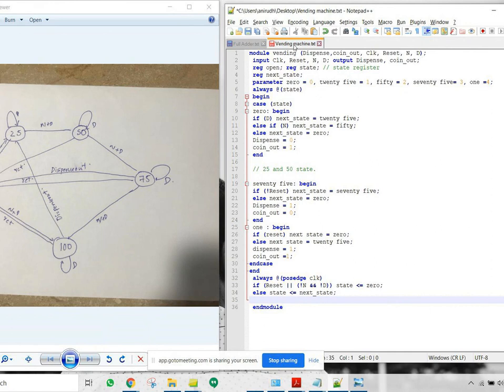One more input I would like to give you is, if you've done any programming before, you should indent the code properly. So there should be spaces between two lines. Then it should be starting at the correct column number. So always begin in the same column. Then anything between begin and end of the always block should be one column inside that. So from line number 8 in this case to line number 14, for example, should be one tab inside the whole thing.